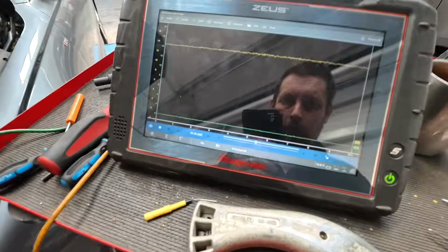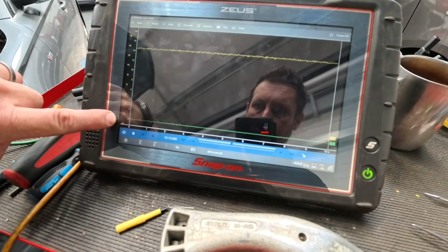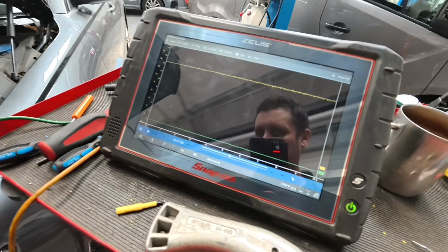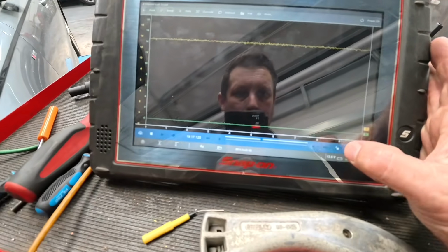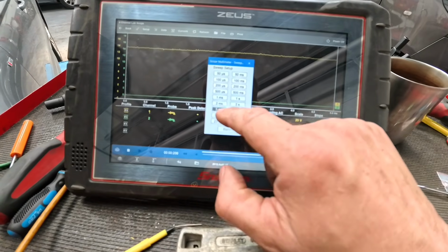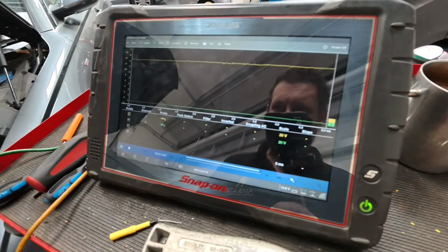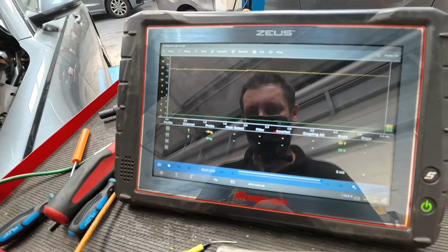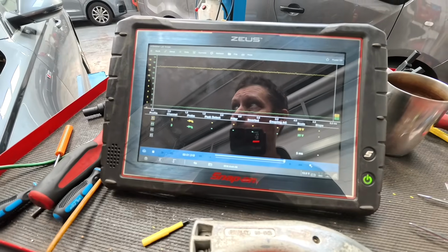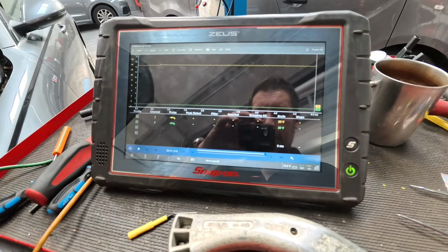This is the one that is a little bit odd for me to see at the minute: we've got 0 volts and 12 volts, so it's grounding that component all the time. There's no pulse width modulated signal. No matter what speed we've got it run on, it's permanently holding that to 12 volts. So I think our next step is we definitely need to get into the top of that solenoid valve and make sure the circuits are right through there. Yeah, next test.